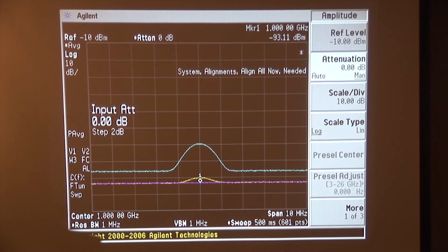And put in the attenuator right here. Now when I turn this amplifier on, I'm hoping to see the magenta trace rise about 3 dB above the yellow trace, right up to that minus 90 dB line, 2 divisions from the bottom. If I did my math right, it should be about right when I do that. Turn the amplifier back on. Yeah, I overdid it just a little bit actually. I've got a little too much loss in there. So that's all right. Just sit here and adjust it a little bit.